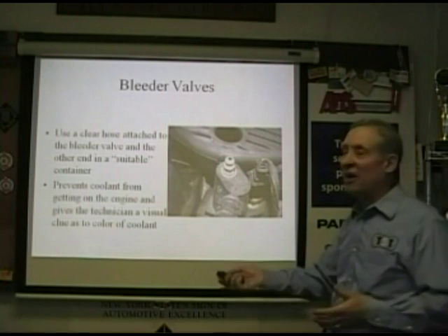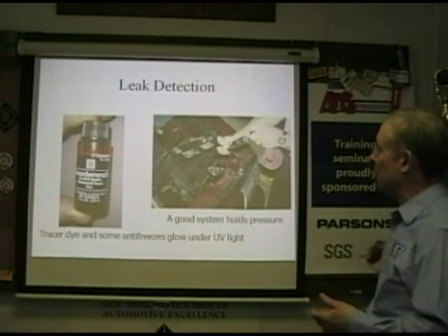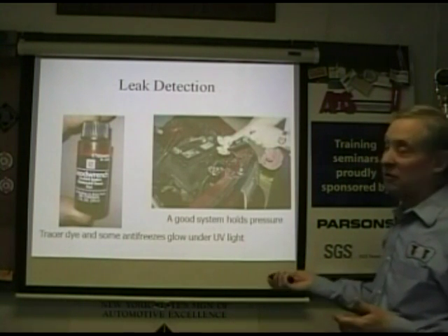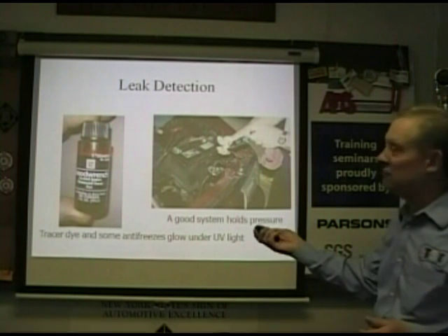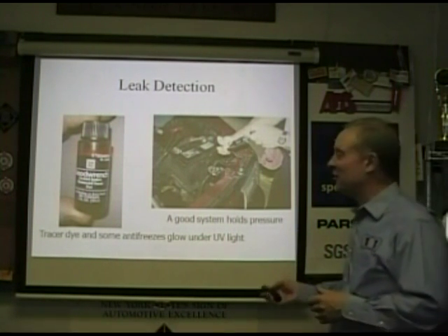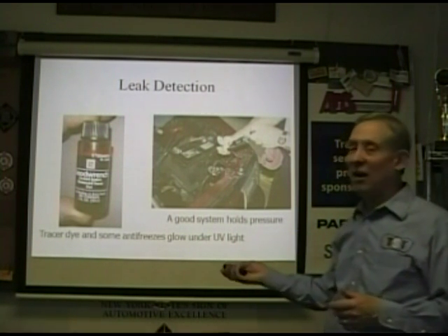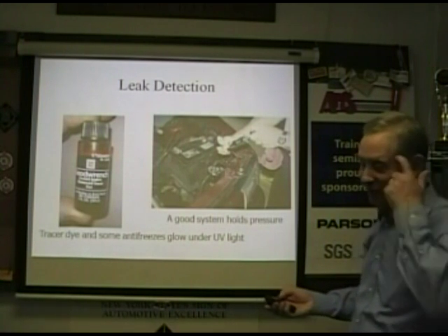Use bleeder valves. You just got to make sure it's bled. Got to be pure. Dye's a good way to find leaks. I love UV dye. Good stuff. Make sure it's the right dye for your system.